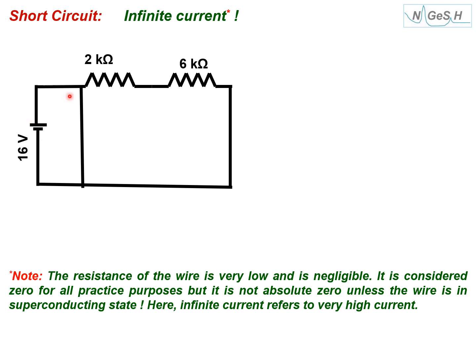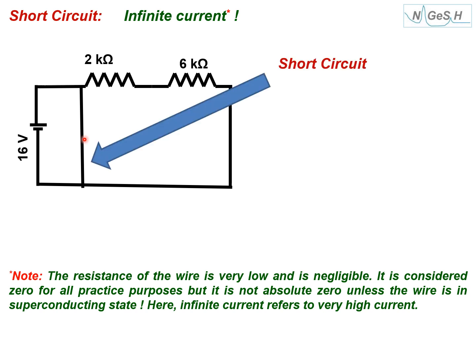And so this will melt and burn, and then something can happen. This is short circuit. This is what people generally refer to as short circuit, and you should not do this. We should always be careful, particularly when you are using diodes. That's why we recommend always having a resistance in series, because a diode, which you will learn later, when it is conducting, becomes almost like a short circuit. So whenever you're connecting a diode, remember to keep a resistance at least to limit the current.